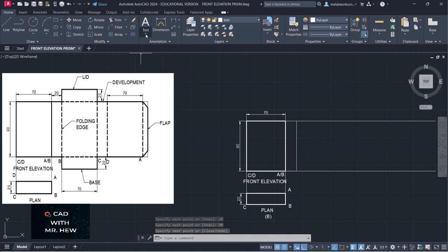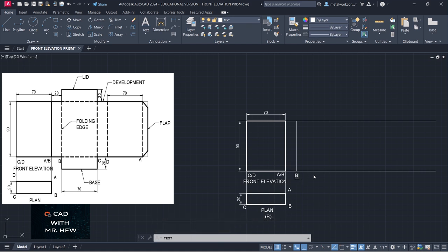All right, so let me label it for single line text. We're going to turn off snap. So right here, enter to accept the default of 6 millimeters, 0 rotational angle. This point here is B. All right. So coming across now, this we're going to measure BC, which is what?